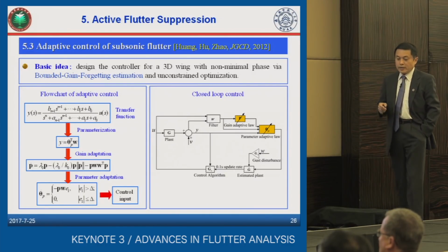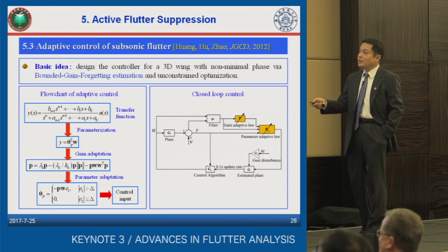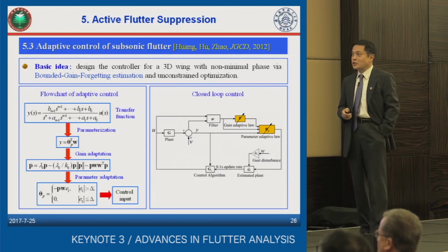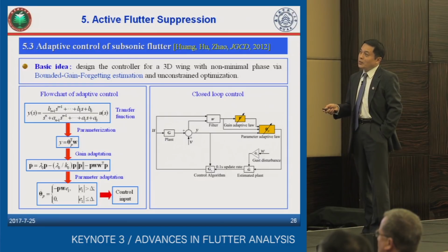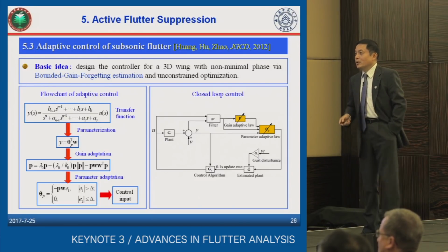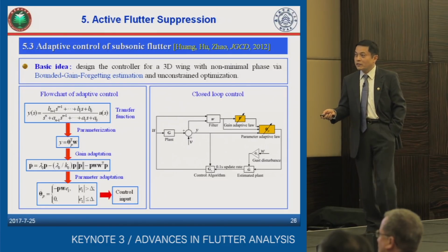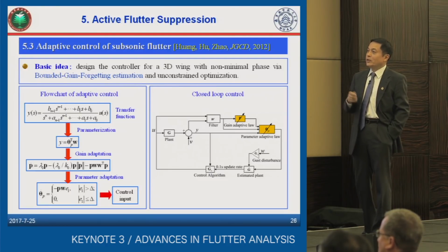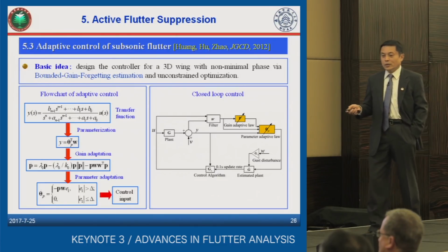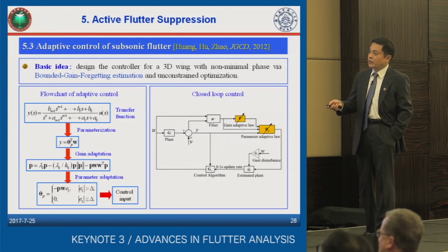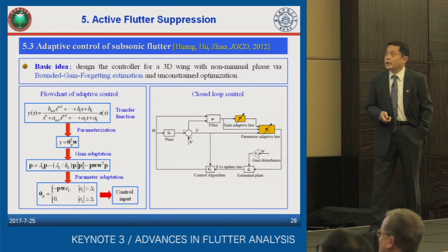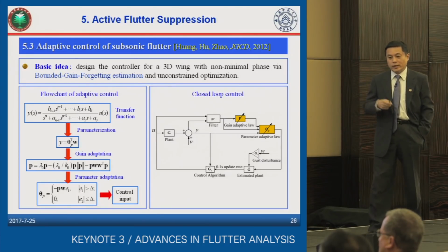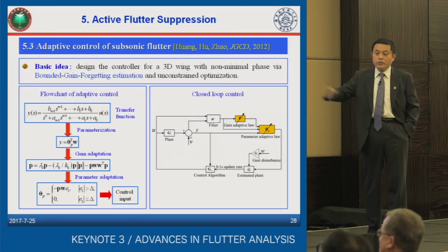And since the system is linear, we only need to update the parameter theta here, step by step, according to the variation of flight conditions. Then how to design the change of theta? We suppose that the derivative of theta is proportional to both vector p and the error e1. And here, we let p yield a set of differential equations so as to get the performance of bounded gain forgetting estimation, which means that with an increase of time, we will forget the old things.